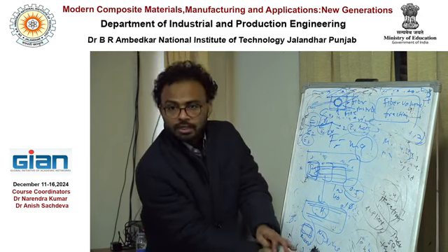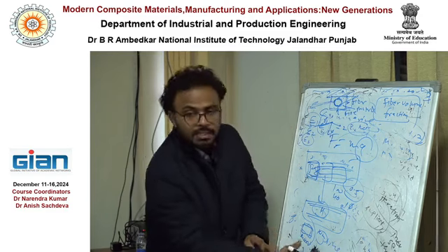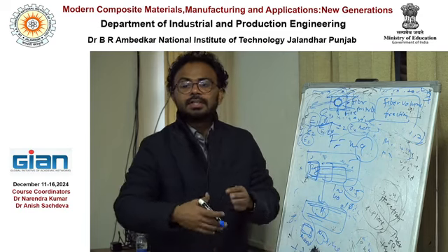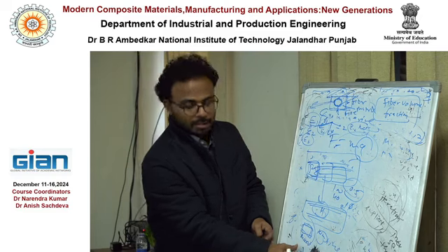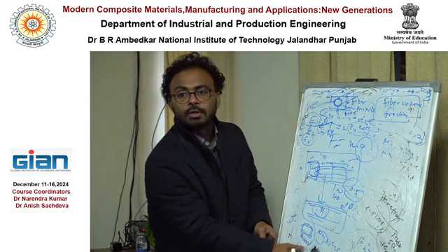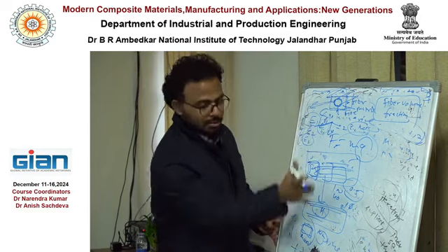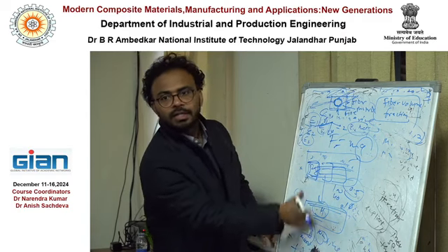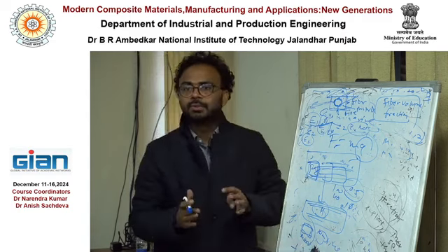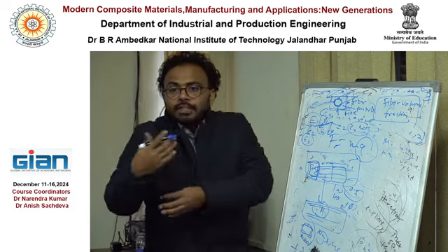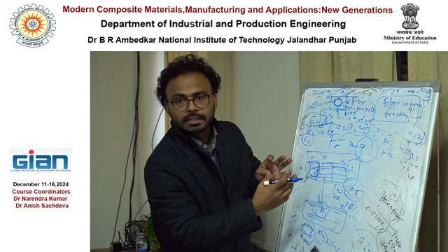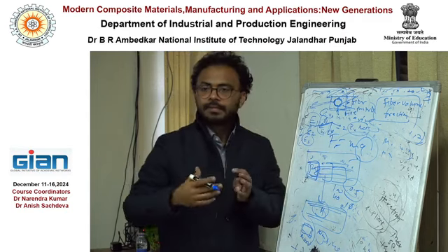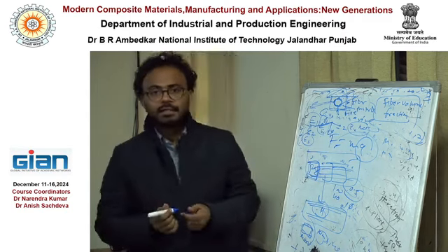So understand a little bit of RBE, apply the RBE, get the mechanical properties, apply the mechanical properties here, failure strength here. After that you get the result from here, the design result or the stress result, and whatever is coming from your design part, you will get here, the macro part. And it is not a composite one, it is a homogeneous part. This is homogenization. It's multi-scale modeling, micro to macro, okay? This is the way to do it. And the opposite way, the reverse way, is to do the analysis here and get the result here by the deformation, right? This is the reverse one, right? Okay. Getting the point?